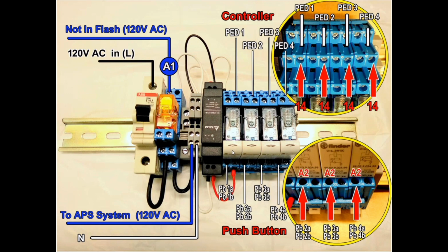Okay. You can see that on the DC relays, these 24 volt DC relays on the right, the 4 of them, you could have a relay module which has 2 relays, 1 relay, 4 relays, and even more, depending upon what the requirements are of your particular intersection. You put 1 relay per crossing, for each independent crosswalk. So what you have is push button 1 and push 1A and 1B. So that would be the 2 push buttons on a particular crossing.